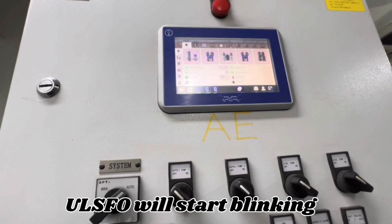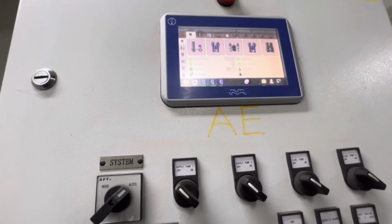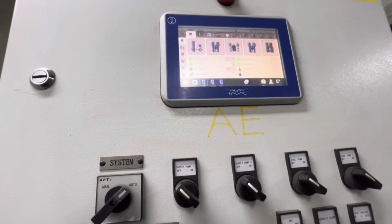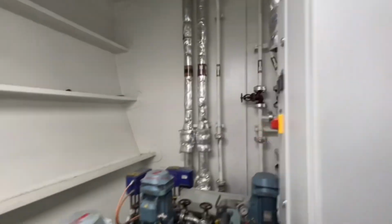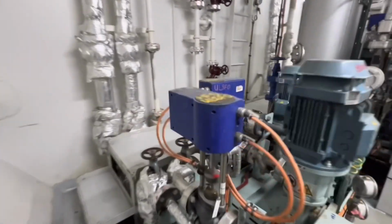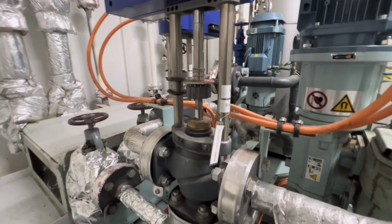You can see guys, it has started blinking. It means the changing over has started. The changeover valve has started shifting from high sulfur to the low sulfur position. Here you can see this is the position of the control valve.